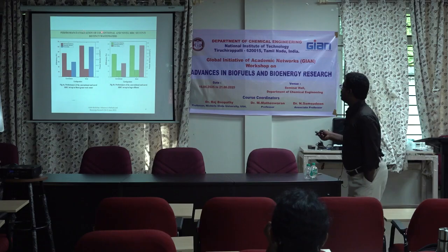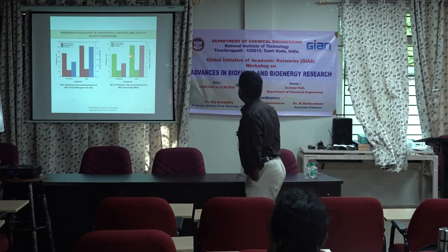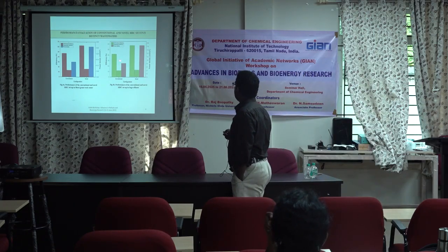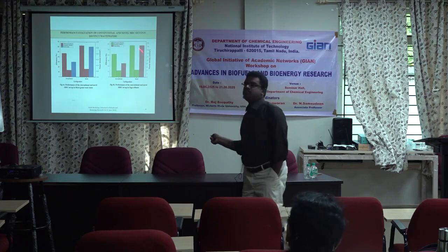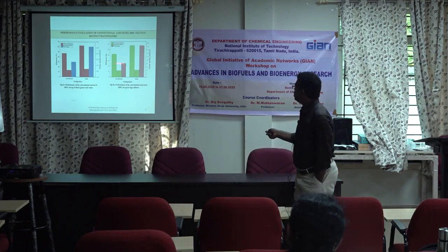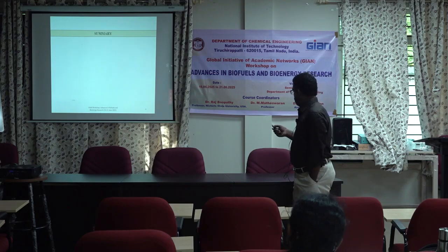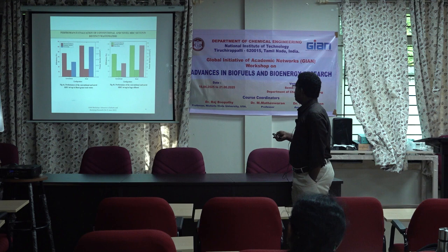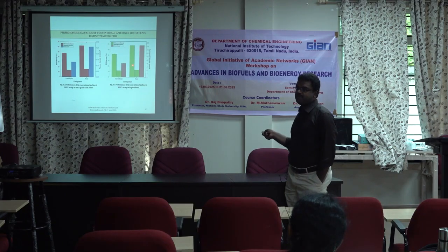Similarly, we tested two different wastewaters with the conventional as well as the patented system, to see how much it improves based on the type of wastewater used. From this we concluded that with the two different wastewaters, sago and black gum wastewater, we achieved a COD removal efficiency of 62% in one, but in the sago effluent the COD removal efficiency was 55%.